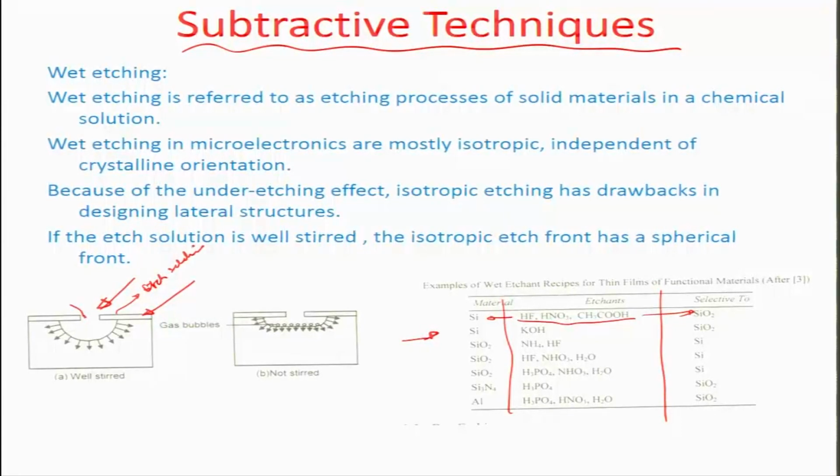So, what you do is you basically create a via in this etch selective layer and put the chemical in close proximity, so that the moment it touches the layer which is supposed to be the etch material, in this case the layer underneath this particular layer, it starts etching away. If it is a homogeneous process with stirring and all those actions, you may expect that all the vertical and lateral etches are equal to each other, homogeneous in all directions, and you will have some kind of a hemisphere emerge because of this etching process.